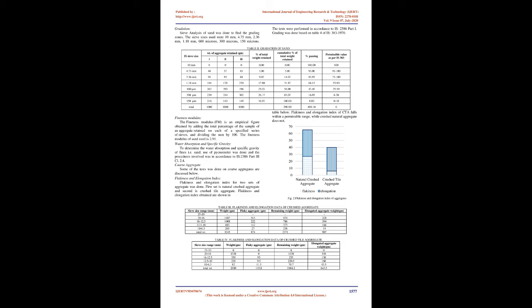Fine and coarse aggregate. Fine aggregates generally consist of natural sand or crushed stone with particles passing through a 4.75 mm, number 4, sieve. The fractions ranging from 4.75 mm to 150 microns are termed as fine aggregate. The sand particles should also pack to give minimum void ratio. Higher voids content leads to requirement of more mixing water.